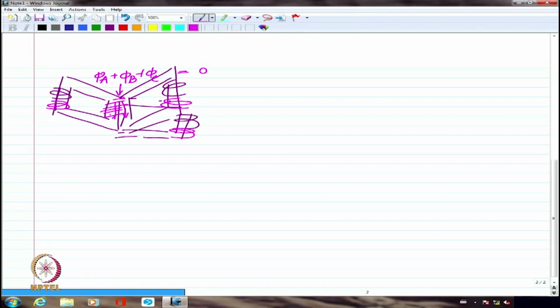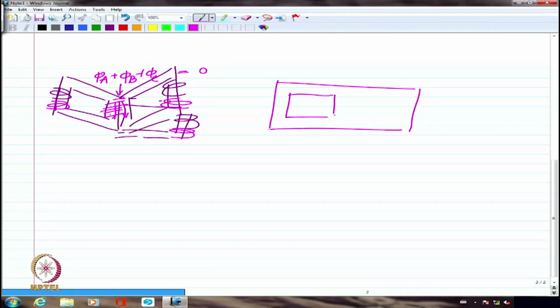That's the reason why normally if we are talking about a 3-phase transformer, the core is somewhat like this. It looks like a shell type construction for a single phase case, but I'm going to have essentially the core somewhat like this. So in all probability, A phase primary wound here, B phase primary wound here, and C phase primary wound here.